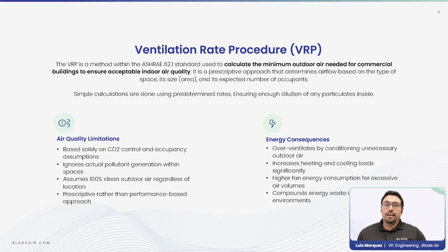Additionally, there are energy consequences, which are quite significant. You're operating heating and cooling systems to condition this outside air, and generally they use about 3 times more energy than just recirculating already conditioned air. And as I mentioned, in the worst case scenarios, you're actually degrading your indoor air quality by introducing polluted outdoor air.